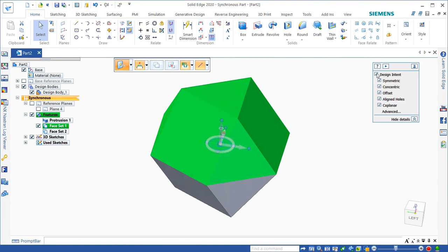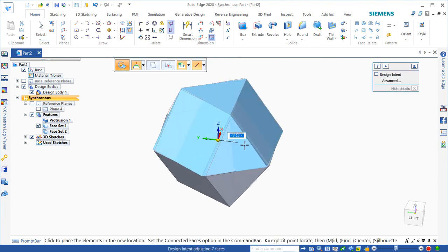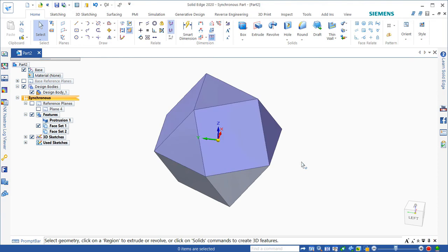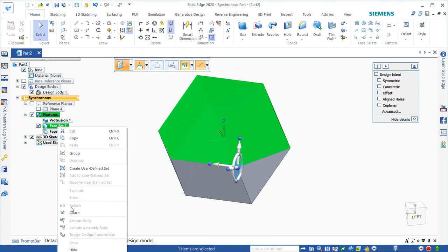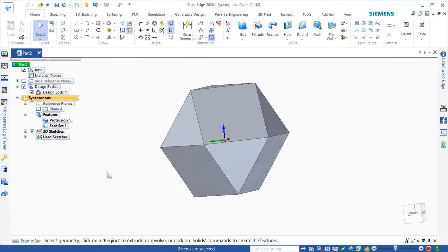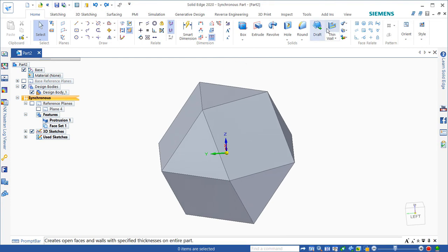Now I can rotate that entire top portion, that reference geometry, 60 degrees. So that way I'll end up with a rectangle or a square over top of a triangle, which is exactly what we want. And so then we can just right click and reattach that geometry. And there we go. So now we have a solid. Now we're ready to create the thin wall.